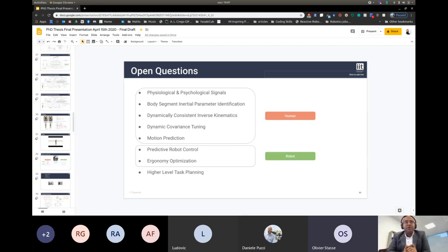Just to check if you're able to, how far you are from the identification that you have done with other means. Yeah, concerning the benchmarking of human joint torques, one interesting way is exactly what you are proposing, where in place of a human model, we actually use our robot model and then benchmark them against the joint torque estimates we are doing currently on the robot.